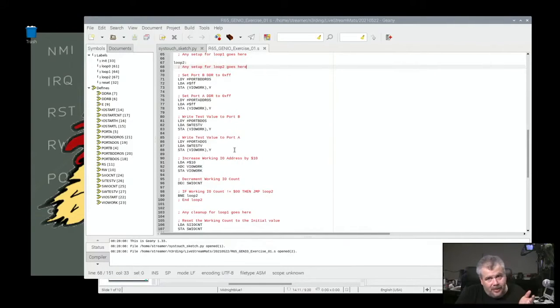And it occurs to me now that it might be interesting to do, as a further exerciser to make sure that the data direction register stuff is working properly, to start shifting that DDR one way or the other, so that we're writing fewer and fewer bits.